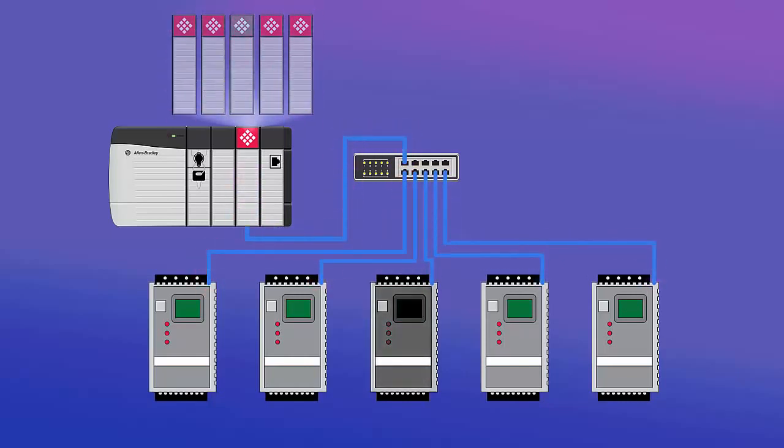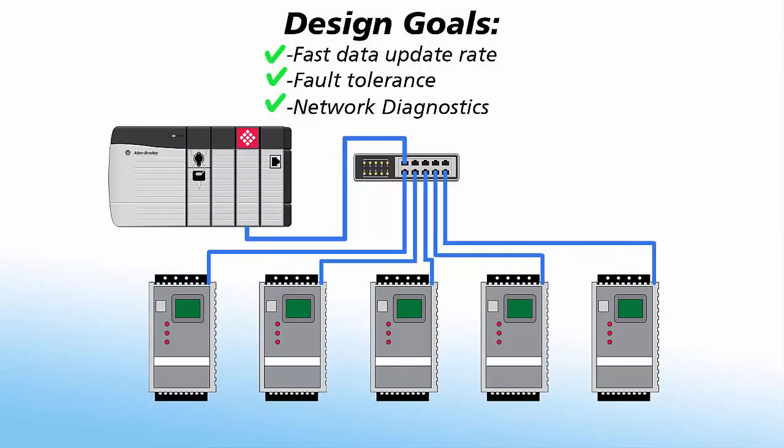In the event of a drive going offline, communication with the other 4 drives will remain unimpeded. Many devices, such as ProSoft's MVI56E MNetC, can support multiple client connections. Also, because our module uses an I/O connection to the PLC, the communications are fast and the PLC has access to communication diagnostic tags to reduce your troubleshooting time in case of problems.